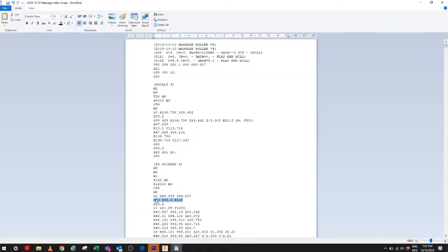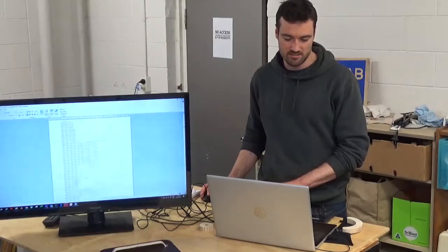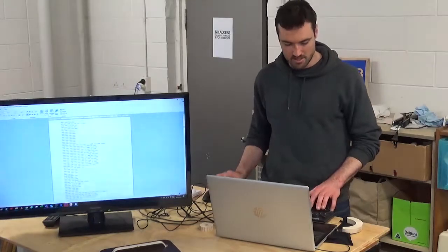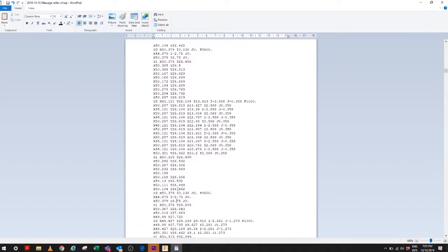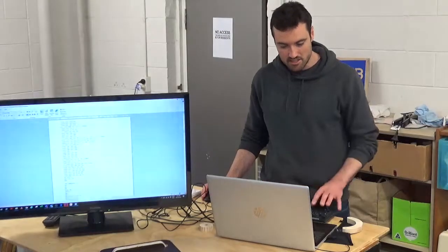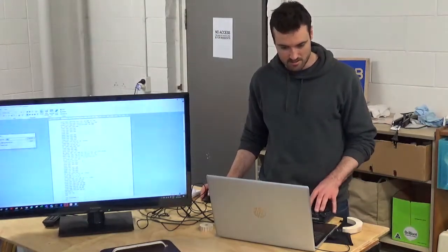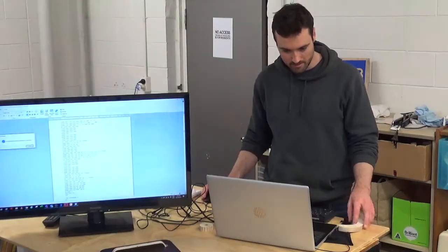I know it sucks. And is it just this machine you're talking about? Yes, every machine has its own particularities. So it's G43. Any line with G43 we want to kill. But there is a fix coming. It did used to work, but something changed with the Python code, and now you have to do this manually. But it's just temporary.